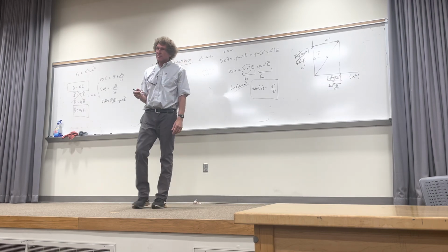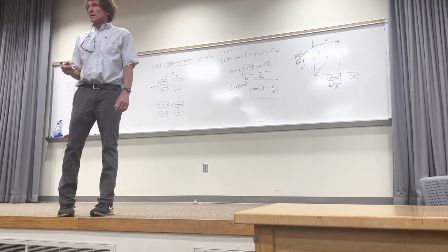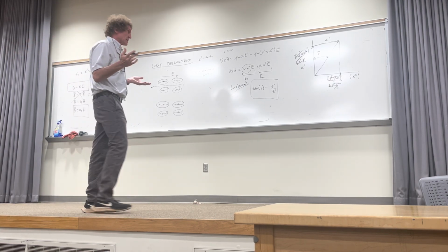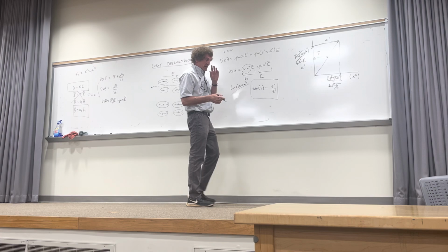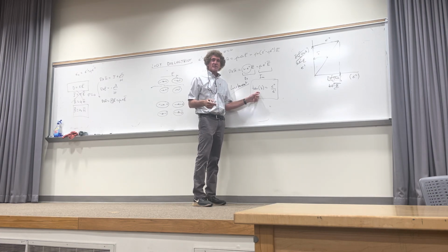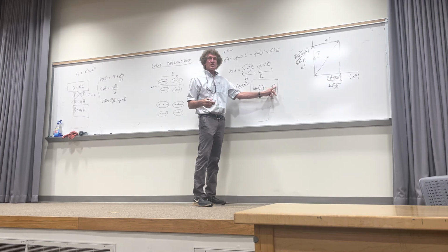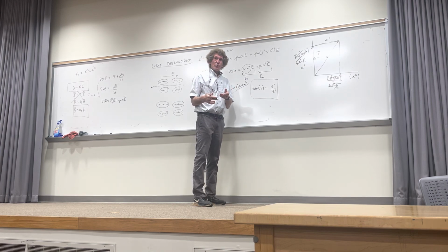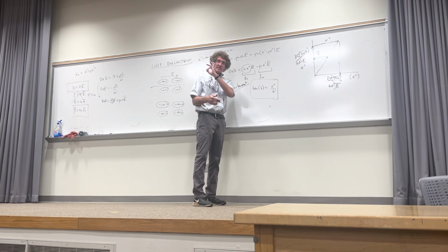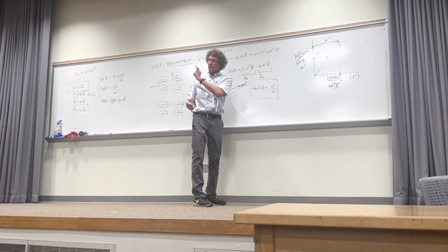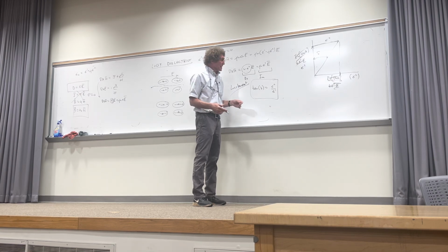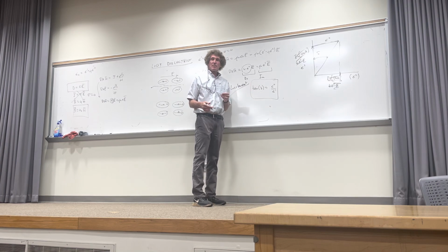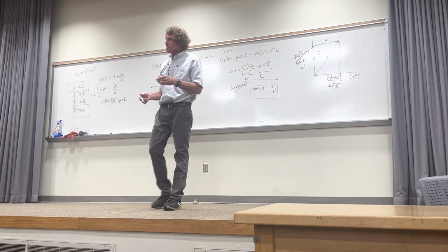Any dielectric that's worth using is going to have some loss. It's just the reality. But you want to make sure at a given frequency that this ratio is very small. Think about epsilon double prime proportional to loss, epsilon prime proportional to energy storage. That's a better way to think of it. So we would ideally like this to be zero, but it's never zero for any real material. There's always some loss. And this epsilon prime and epsilon double prime are strong functions of frequency.